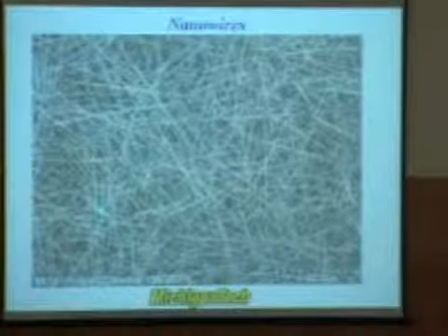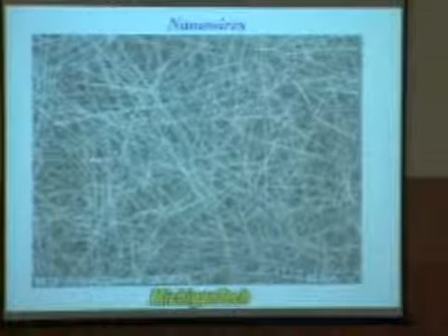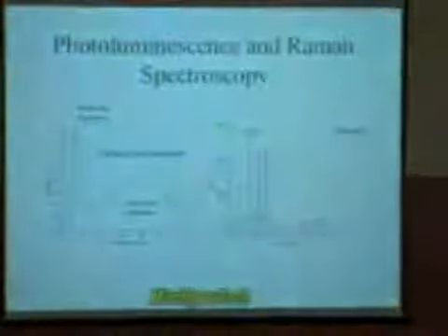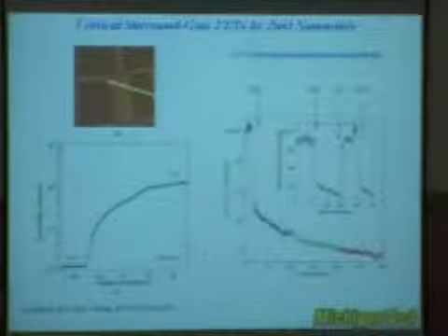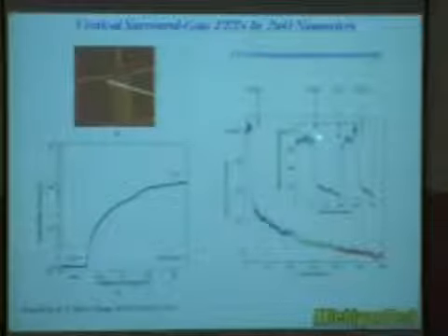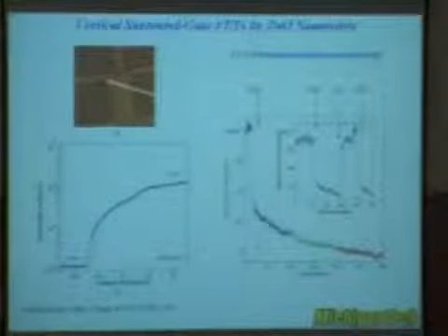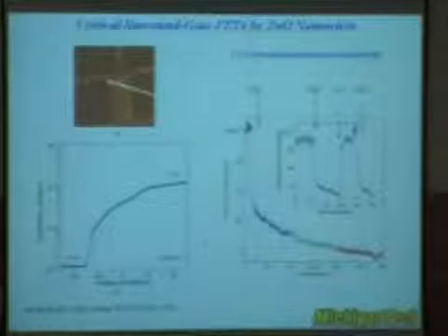This one is grown at 500 degrees Celsius. Absolutely compatible with CMOS technology. You can directly grow them across the electrode if you want. All right, just skipping some of them, it was already demonstrated in 2003 using a piece of nanobelt, which demonstrated the on-off state. And also, it can be used to sense UV light. You can see that if the light turns on here, you can generate the so-called photoelectrons inside the zinc oxide materials. So device, no problem, you can use it.